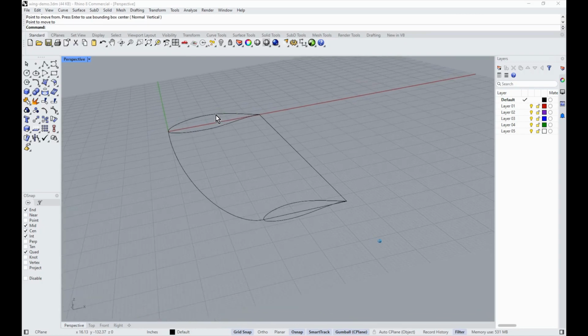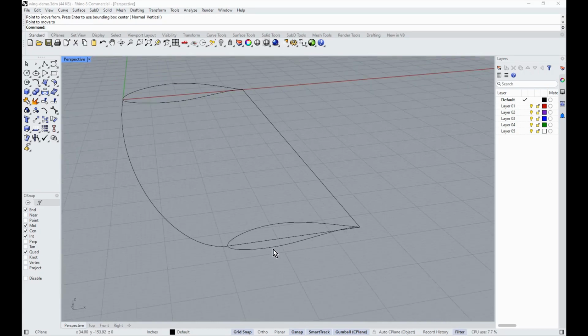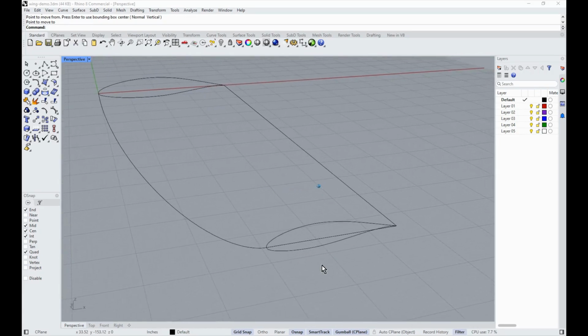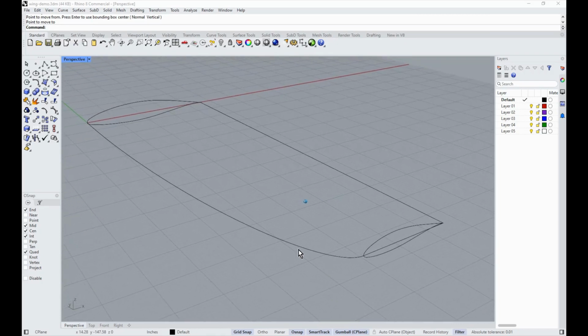So now we have an airfoil 65-415 at the root. Its thickest part is near the middle. That's what that number means. It's like 50%, and then 63-618, it's going to be more like 30% right here. So we're moving the thickest part forward. We're putting more camber in it. We're making it thicker in total. So these are all dials to turn to basically increase the coefficient of lift, especially on the tip to help with tip stall, things of that nature.